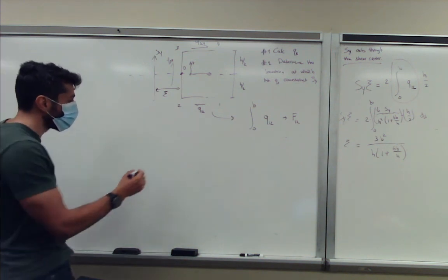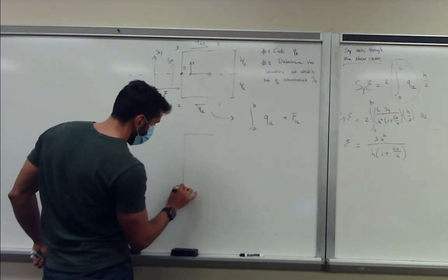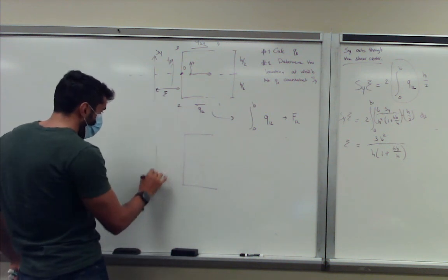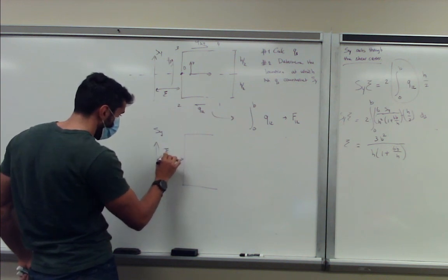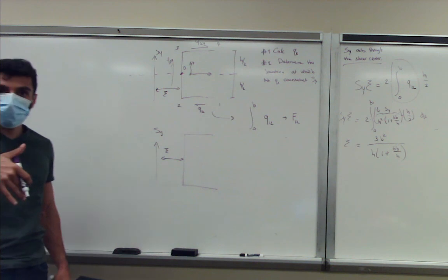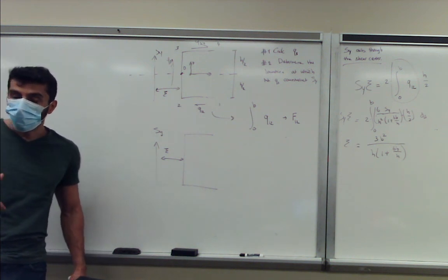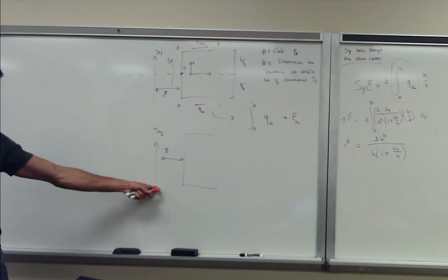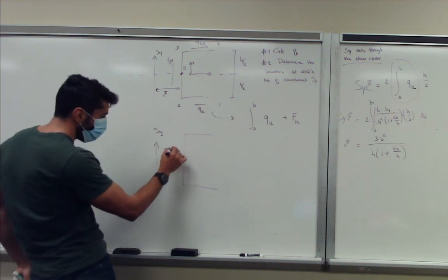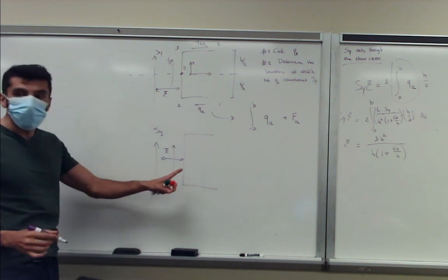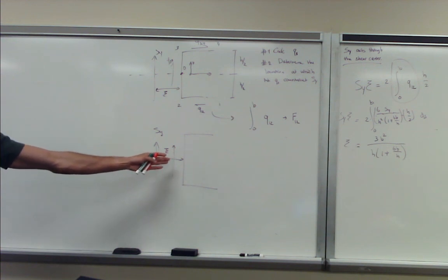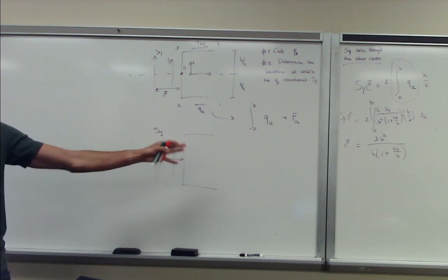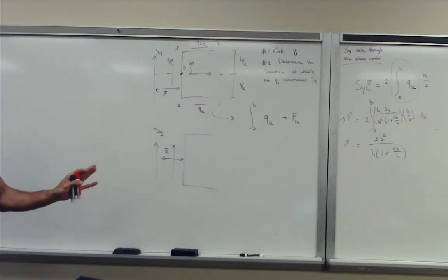So what does it practically mean? It means if you have a C-section, and I apply my shear force Sy at this location, then my C-section bends and bends only. This can be confusing because you're applying a shear force somewhere else. If you applied the shear force here, then you would bend and twist at the same time. You might think, well, how can I apply a shear force in mid-air and still bend? This is just mathematically speaking. So the concept of shear center is in this case more mathematical than practical.